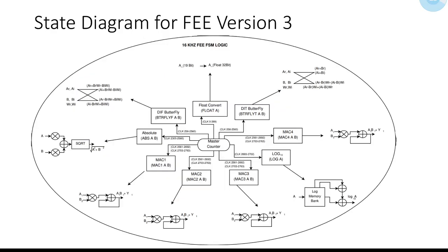The control logic is developed in such a way that the underlying designed hardware can be used for 9 different functions of the feature extraction engine. It is reusing the 4 adders, 6 multipliers, 4 registers, 1 fixed to floating point converter and 1 square root hardware to infer these 9 functions. The state diagram is shown.